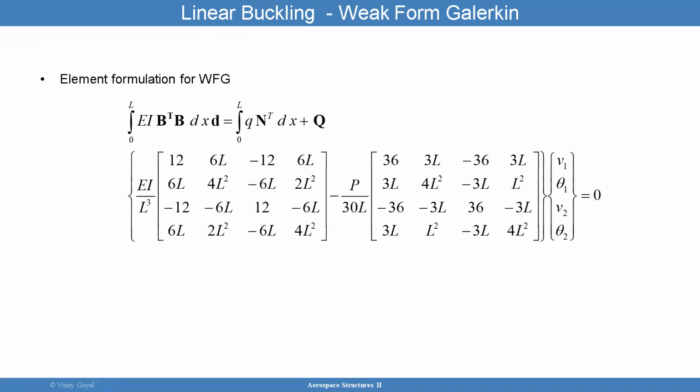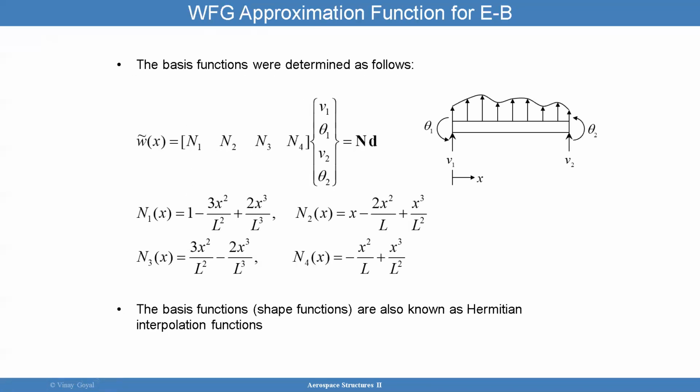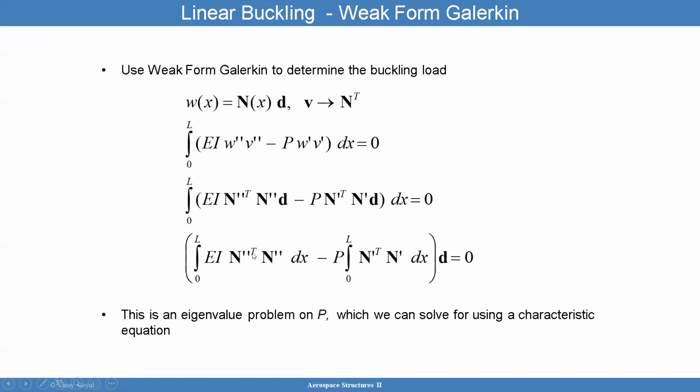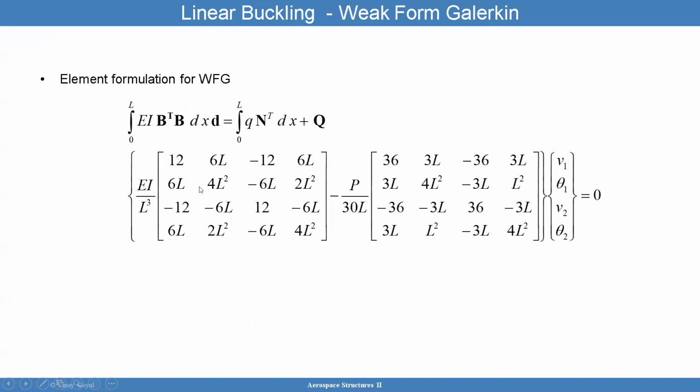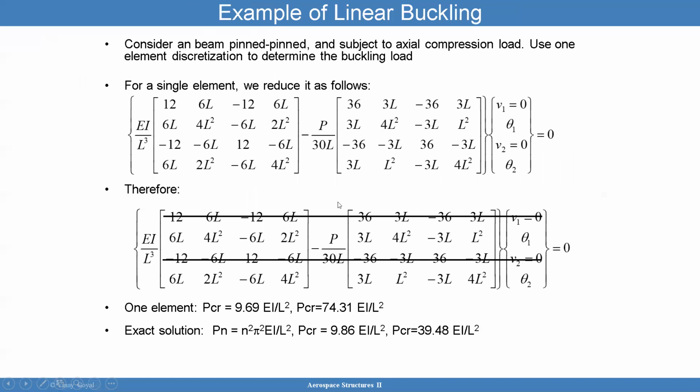And I've done that here. I've calculated what these things look like when you multiply everything out. I don't want to confuse you. This is very easy to do. You plug all this in here, and when you integrate in Mathematica or MATLAB, this is going to spit out numbers, these matrices. P is not known. The length of the beam is known. These are unknown. So now what I need to do is go ahead and apply the boundary conditions.